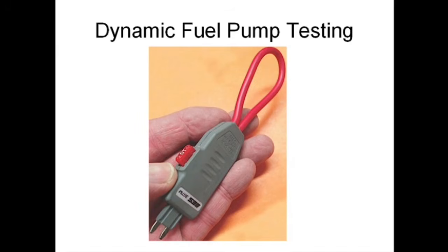Now, to make it easy to get into these different circuits, as you can see here, I have a power distribution box with several fuses. I can use a fuse buddy that will allow the circuit to still be protected with the fuse and also allow me to attach my current probe, giving me access in series to that circuit so that I can current ramp that circuit.